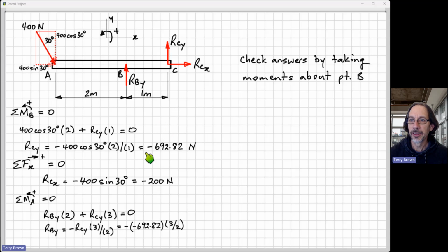Just leave it as it is, leave the negative value there, write your equations of equilibrium according to the free body diagram that's drawn, and then when you need to substitute a value in, you substitute the negative value, if it was a negative value, into the equation to get the correct answer. In situations like this I see a lot of students make mistakes. Put that number into our calculators and we get 1040 newtons.